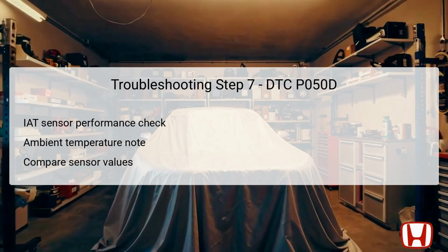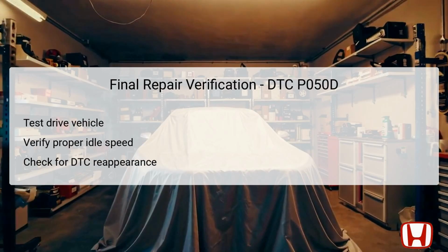If there is a difference of 5.4 degrees Fahrenheit or more, it indicates a malfunctioning IAT sensor or MAF sensor, necessitating replacement. If the IAT sensor is found to be functioning correctly, check the throttle bore for dirt, carbon, or damage, cleaning or replacing as required. Once all necessary repairs and replacements have been performed, it is vital to conduct a final repair verification. This involves test driving the vehicle under conditions similar to the initial complaint to verify that the idle speed is now operating correctly.